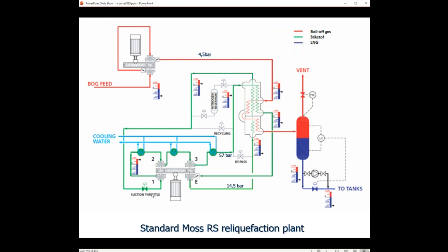These vapors are compressed a first time, and then we already reach almost 100 degrees. That's quite hot. If we compressed that immediately a second time, we would have temperatures which are not allowed for the nitrogen. So after the first compression, we pass through a heat exchanger and cool down the nitrogen under pressurized conditions.